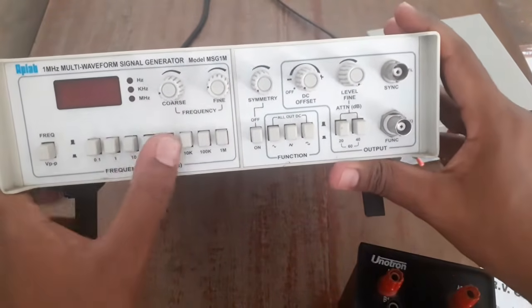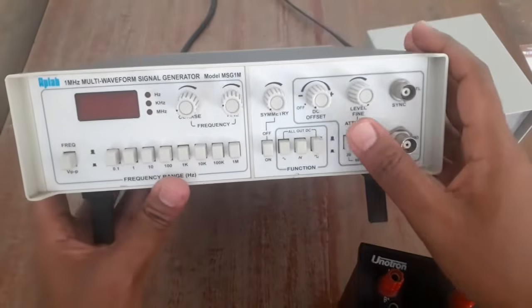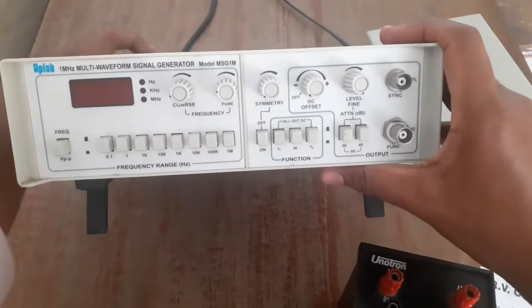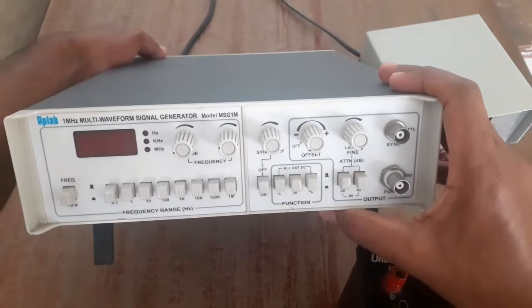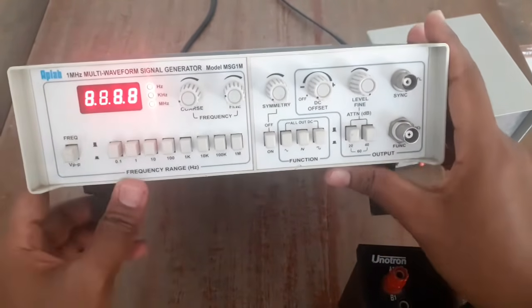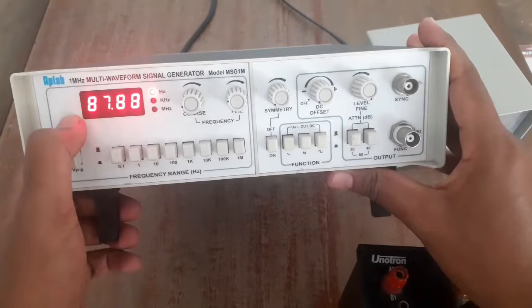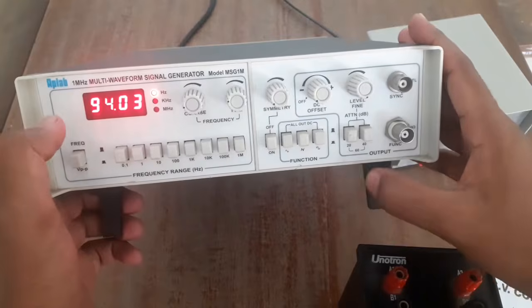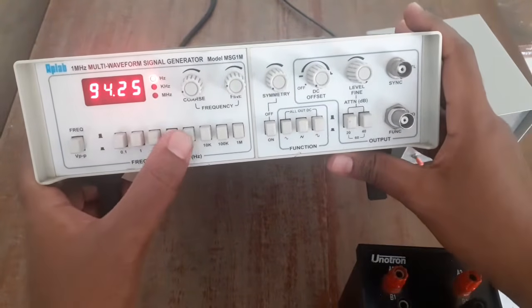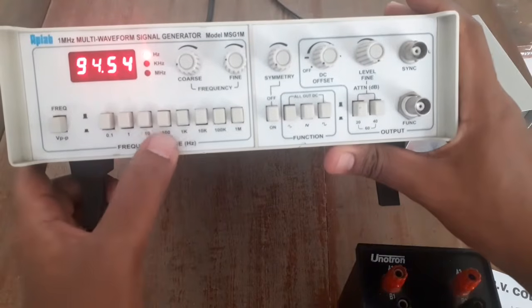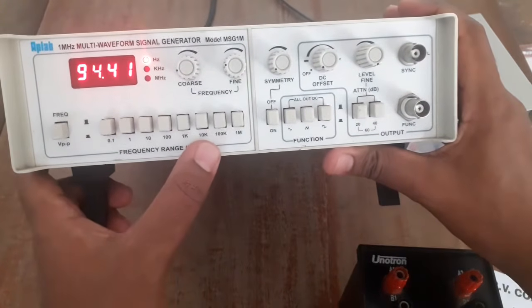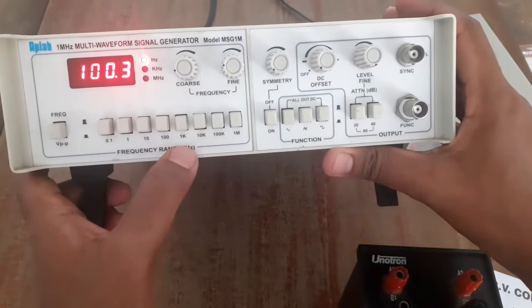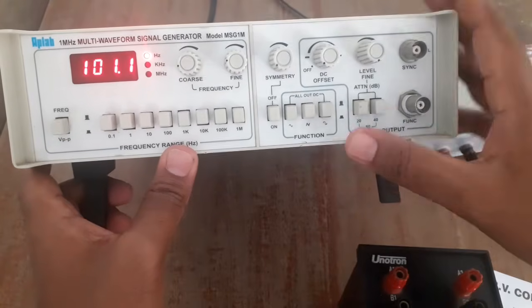Fine, for the settings, you should have some preliminary settings for the signal generator. The settings are as follows. I will switch it on first. Usually the button is on the back side. You can turn it on. The display is showing the frequency of the AC which it is producing at its output, and the frequencies can be selected through ranges. You can see it is written 10, 100, 1K, 10K and 100K, which means if you press, for example, this 1K, then you can have all the frequencies running from 1 Hz to 1 kilohertz.